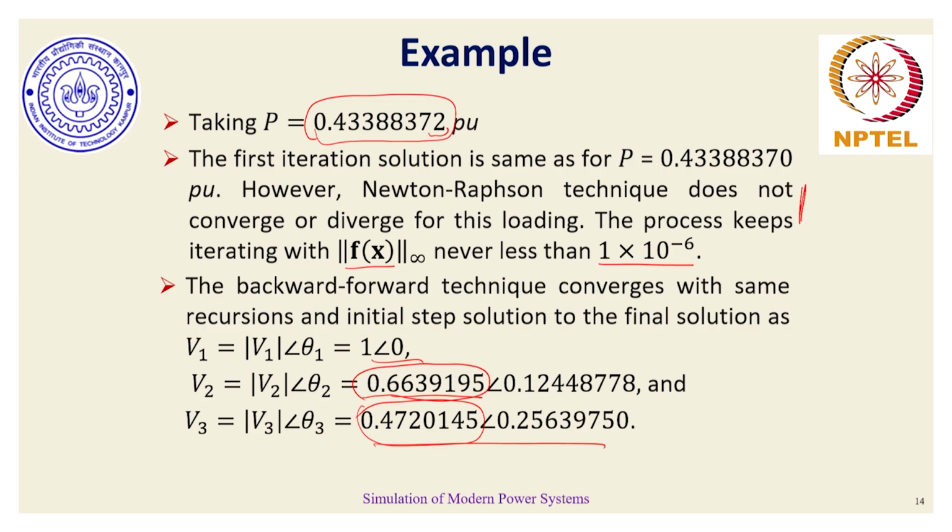Operation is not the main point. The point is, will we be able to find the solution from the NR method? Absolutely not, because the load values and voltage values are getting closer to voltage instability, which we will discuss further when we take up the module on voltage stability.